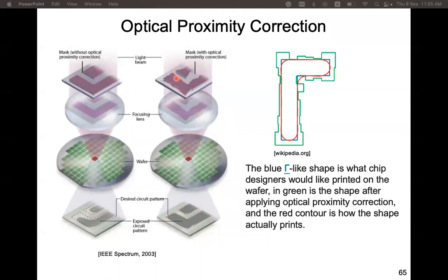Now the manufacturer uses this kind of mask, applies OPC techniques. Then after the exposure to the light, this pattern is developed, which is very close to the desired one. So this is the first technique, OPC, for deep UV technology for resolutions at 65 nanometer or below. Actually, even from 90 nanometer technology, this OPC technique has been applied.